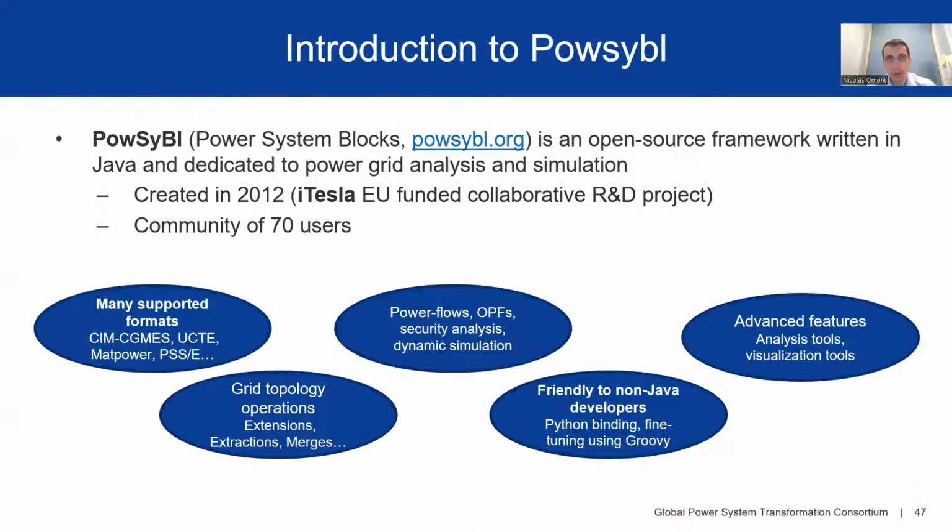So just a few words about PowSyBl. PowSyBl is an open source framework written in Java and dedicated to power grid analysis and simulation. It was created 10 years ago through an EU-funded collaborative R&D project, and it now has a community of 70 users. It allows you to perform power flows, optimal power flows, security analysis, and dynamic simulation, among other computations. It supports many formats: CIM-CGMES, UCTE, MATPOWER, PSS/E, and